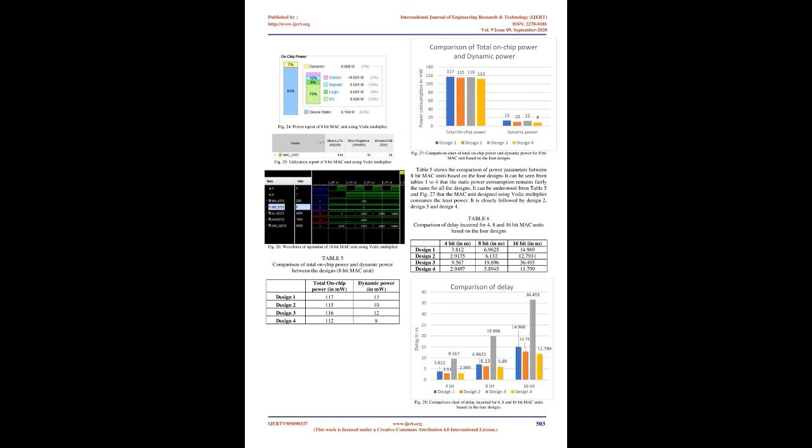Vedic multipliers of larger sizes can be constructed by duplicating 2x2 Vedic multipliers and adding the products using a ripple carry adder. This is shown in Fig 5, where a 4x4 Vedic multiplier is constructed by using 2x2 Vedic multipliers and ripple carry adders. Using reversible logic gates like Peres, Feynman, DKG in the design can further aid in the reduction of power consumption. An implementation of a 2x2 Vedic multiplier using Peres and Feynman reversible gates is shown in